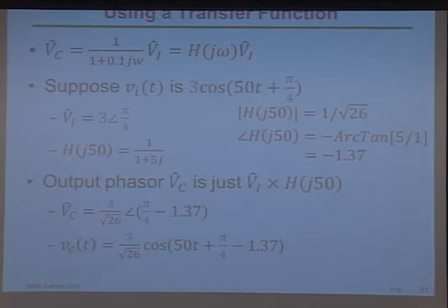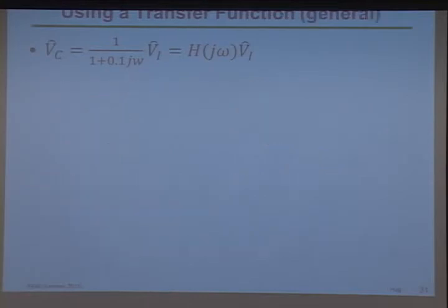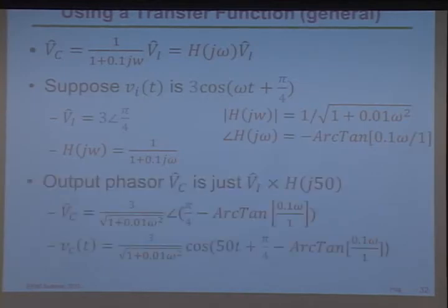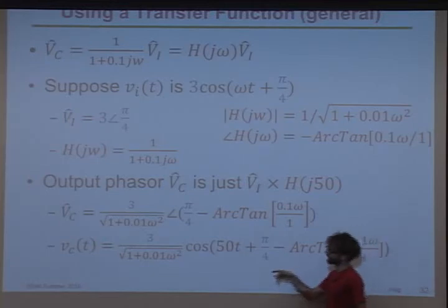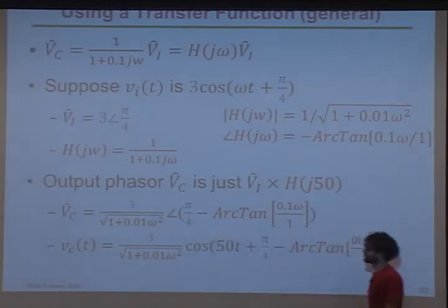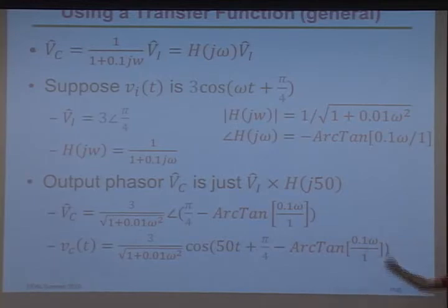Like, I want to know how it responds to the signal. Now, in practice, you'll never do this because you're not going to want to know how it responds to this necessarily. And so we usually think of it more generally. You just plug in some omega, same kind of deal. And so this overall function, like the overall circuit, as a function of the omega, is going to scale by the magnitude of the transfer function at that frequency, and it's going to delay it by some amount, which is based on the frequency of the signal. Okay? So hopefully that makes sense.